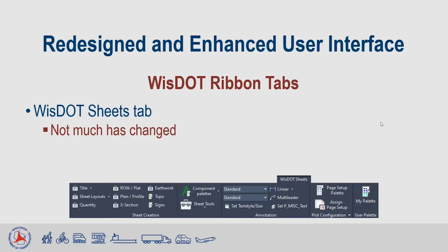The annotation panel includes access to WisDOT text styles, multi-leaders, and dimensions. And then finally, we have the plot configuration panel. It includes a page setup palette, so you can quickly import page setups for your plan sheets. And then we include an assign page setups tool that we've had for some time now that makes it easier to assign a page setup to multiple layouts at one time.